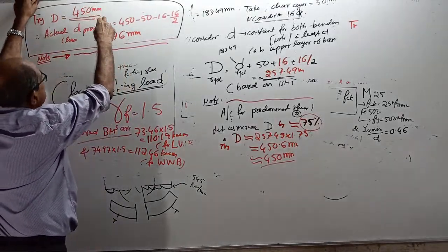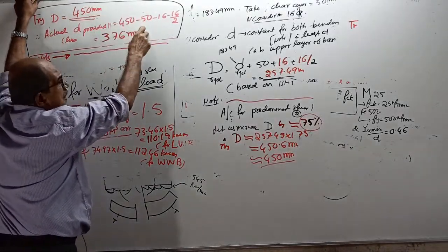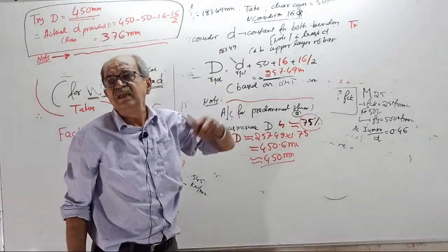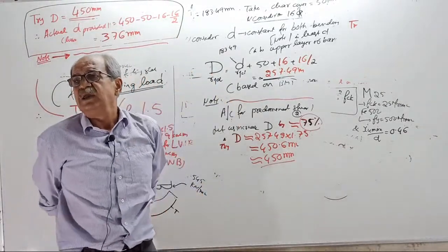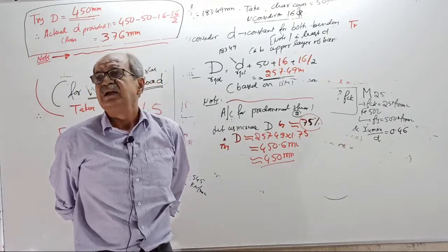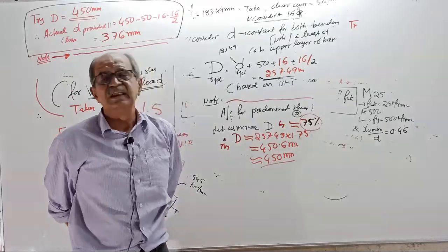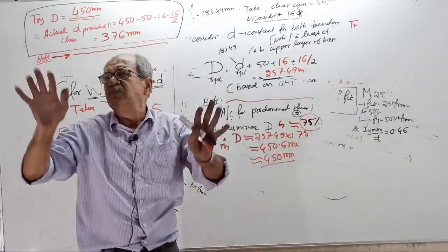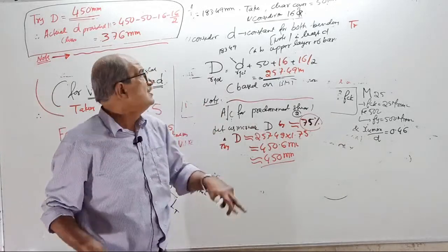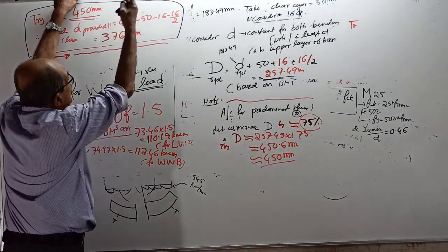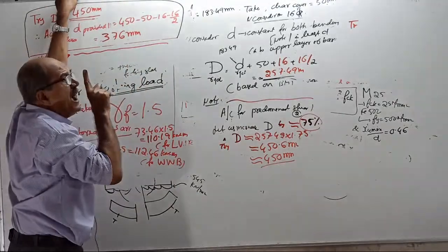Now we got the depth. When you provide this depth, we first considered bending and got the effective depth for that one. In one direction, D is more, other direction, D is little lesser. For the safer side, for both of them, we took the smaller D. So we will take D 376. Someone will tell, other way 12 more is there. Keep quiet, I will tell him.